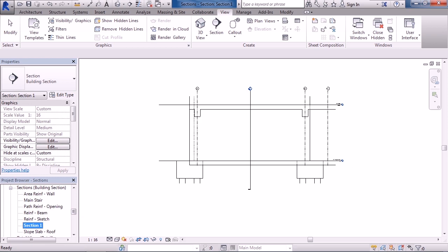We looked at the section name, the graphics settings, and also the actual discipline. From there, we went to the section view, and we modified elements within the section view. We modified the crop, turned the crop off, and again, we looked at the properties of the section. Lastly, we applied a view template to the view to control all of the visibility graphic settings based on the template.